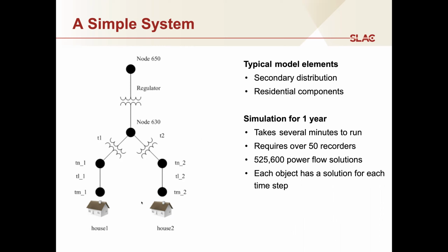So if you were to fully instrument a network like this, you might have to use recorders. These are devices, agents, objects in Gridlab-d that perform data collection for you. And so if you were to run, for example, at a 1 minute time scale, you'd get something like 500,000 power flow solutions over, say, maybe 50 recorders to get all of the data that is coming out of this simulation.